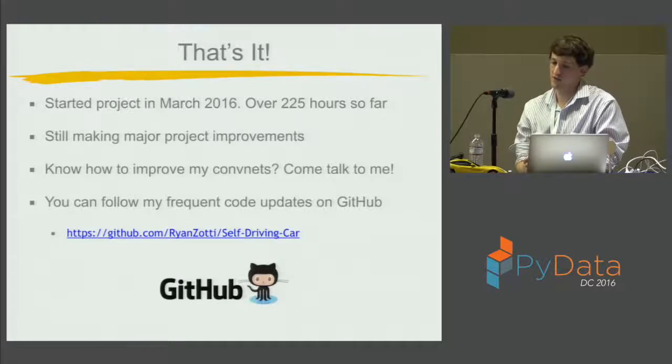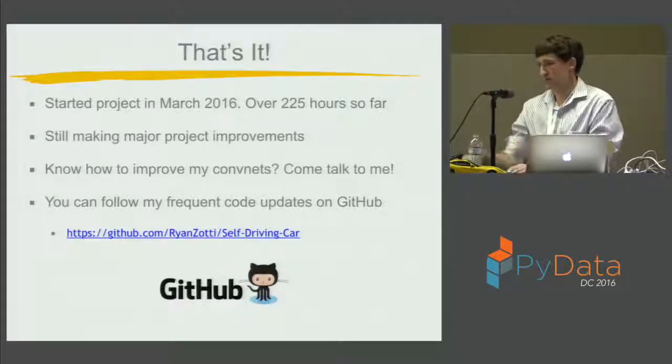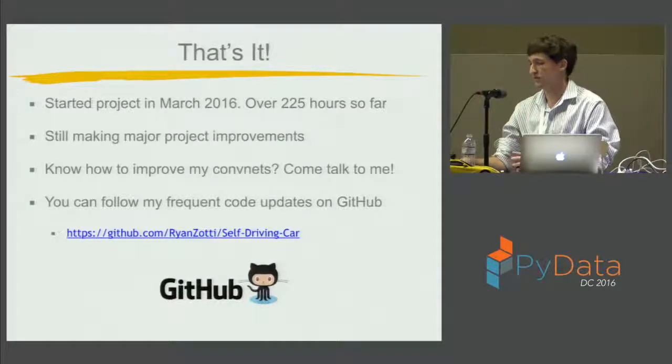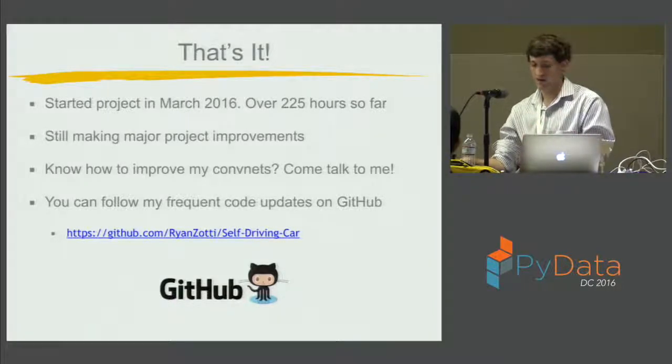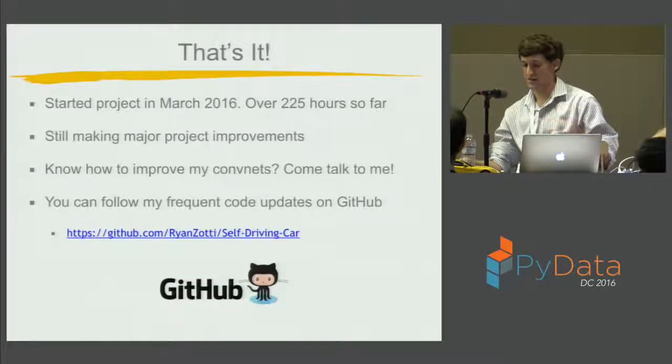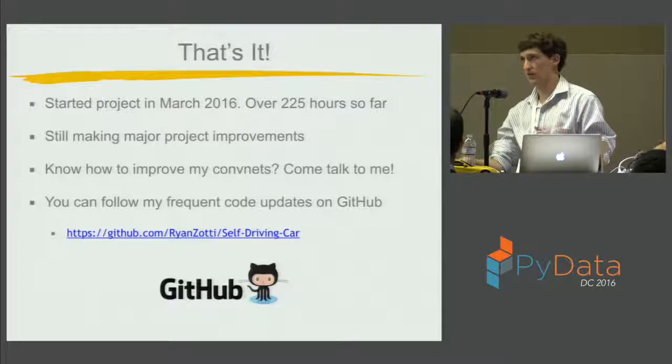I had to do a lot of training examples on that because with latency and everything, it has to be able to correct itself quite a bit when I deploy it. That's probably one of the most complex pieces of my project: how did I actually collect the data? I had just 3 commands: forward, left, right. I did that from my keyboard on my laptop. I set up a Tornado Python web server on my Raspberry Pi. It's really lightweight, very fast, and asynchronous, and it would listen for these commands, left, forward, or right, pass those on to the motor, save those commands to a text file, and then simultaneously save the streaming video to an MOV file.